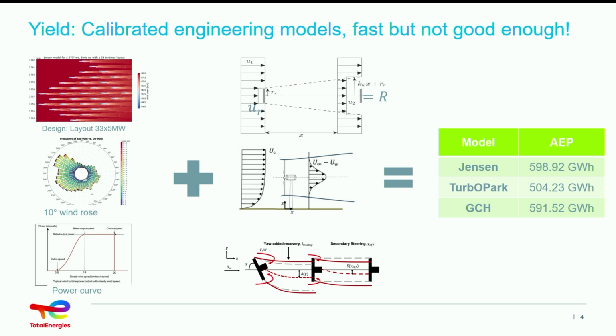But perhaps you will also need simulation to recompute some data at, for example, the hub height of the turbine. Typically, those data are at 10 meters or higher altitudes. But if we want exactly at the hub height, 100 meters for example, we need to recompute this with a CFD software. And sure, after that you want a design of your farm with a layout with the least possible interaction between turbines, and the better cost of construction, the lower the capex, to optimize the levelized cost